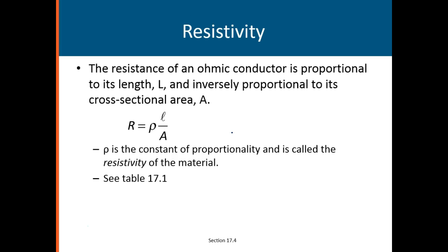No, it's going to be less, because the resistance of the hose for all the length of that hose is just more and more, and that's going to cut down and increase your resistance to the water flow. So it's directly proportional to the length, but inversely proportional to the area.